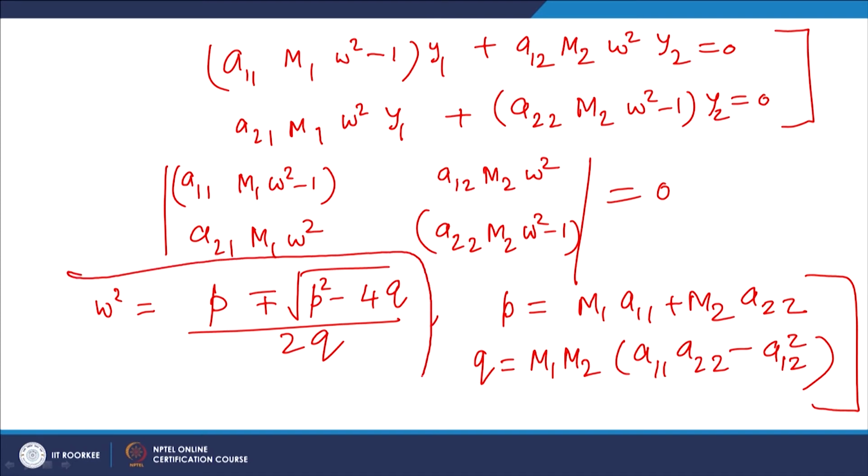So we can see this expression. Because from this expression we have obtained omega for critical speed, and here we see that there is omega square, so we will get two positive values of omega. So when we take the negative sign, we will get the lower critical speed, and when we take this positive sign, we will get the second and that is higher critical speed of the shaft. So using this method we can find the critical speed of multi-rotor shafts. So here we can see the shaft is in the vertical plane.